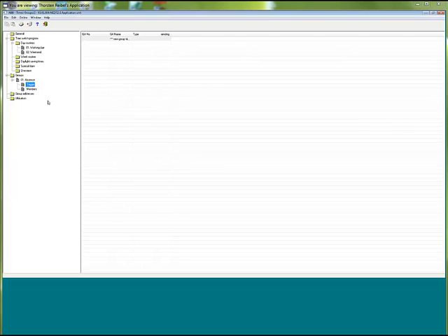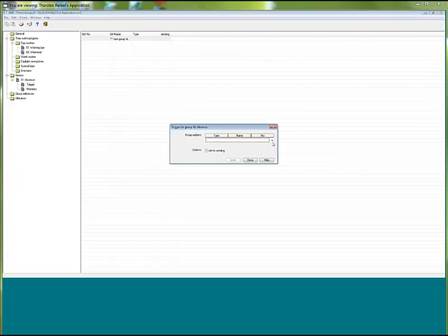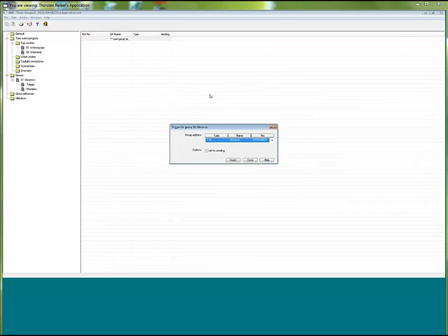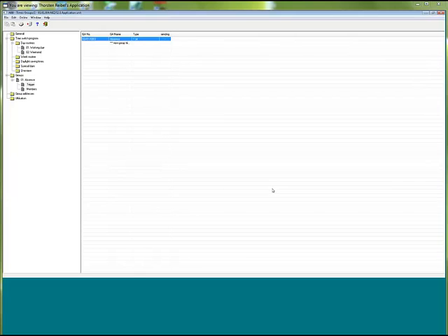The trigger is a group address to activate the group. Principal again, a group address. So let's take any group address. I take a new one I have created already in the ETS. You see here my group address absence. I accept this and insert this, of course. And now it's inside. So this is my group address 313, which can trigger a group, whatever it is.